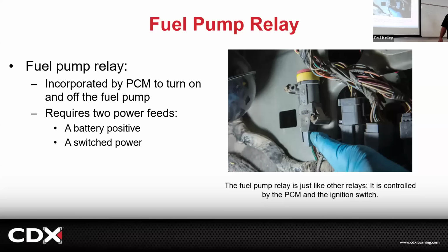Yeah. Okay, now moving into some more of the control side. What turns the fuel pump on and off is typically going to be a fuel pump relay. Now, sometimes they have another thing I wanted to point out. Like if it's a relay, the PCM will control the relay, but the fuel pump draws a lot of amps, you know, like 10, 15, maybe even closer to 20 amps. The PCM doesn't want to handle 15 or 20 amps. The PCM can turn on and off a relay, and the relay will handle the 15 or 20 amps to run the pump. Okay, so typically the relay controls it, just so everybody's all clear.